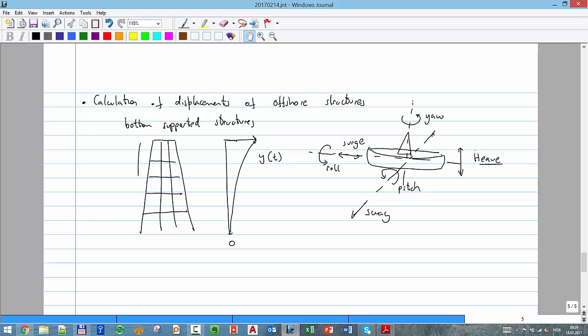And if you have, for example, a spar, remember the spar looks something like that, and the pipes go inside the spar. The movement in that case, the pitch, if we move like that, will cause some stresses on the piece of pipe that is leaving the spar, because that part moves differently than the part that is inside the spar.